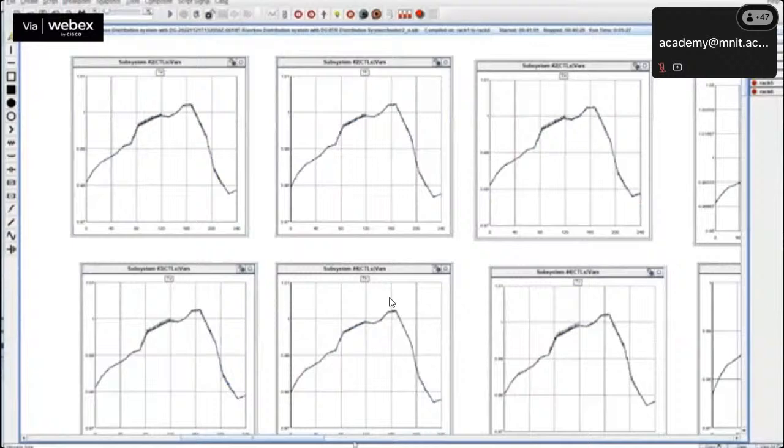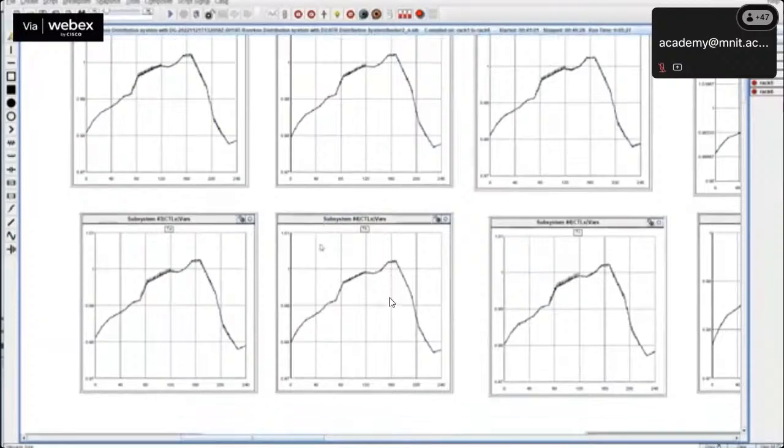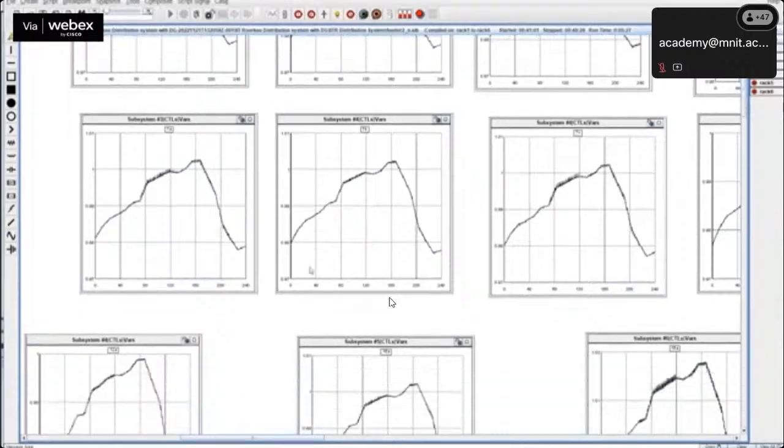To validate the performance of the control strategy of the battery, we will first observe the voltage profile of all the 415 volt nodes in the RSCAD runtime window. By simulating the entire IIT Roorkee distribution system, the voltage profile at different locations for varied solar irradiance, temperature and loads is examined.